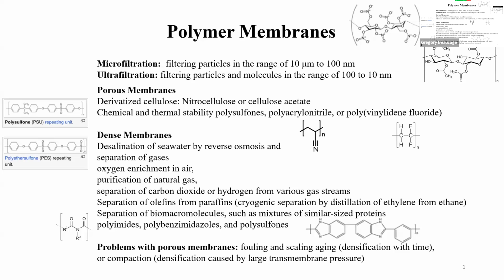So basically membranes are one option, usually the most expensive option, but in some cases the only option. Like for reverse osmosis of water, you can do things like just heat up the seawater and then just collect the condensate, and that's pure water. So you've separated salt water. The problem is that doesn't exactly produce huge quantities. You can set up systems where you have solar driven distillation columns to separate seawater to make pure water. And that's been implemented in some places, but the vast majority of places use reverse osmosis, even though it's more expensive, because you get the quantities out that you want.